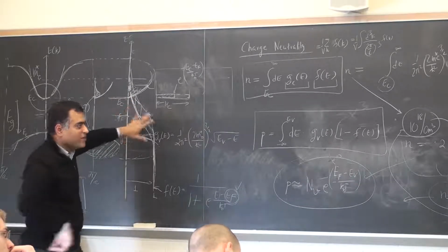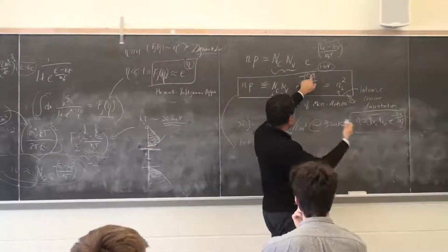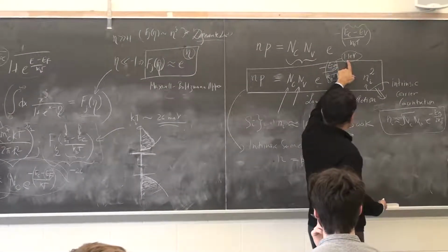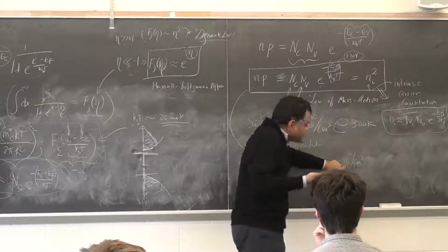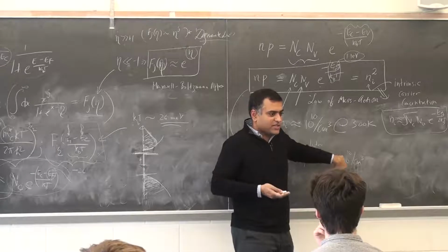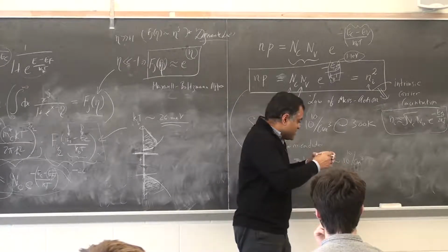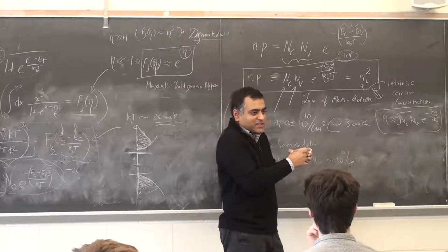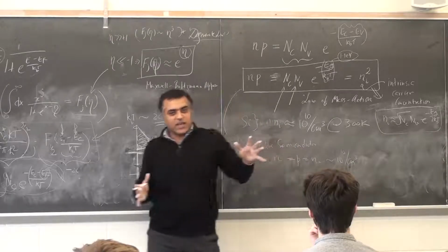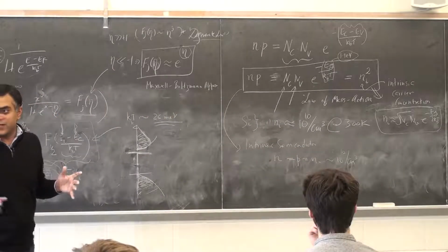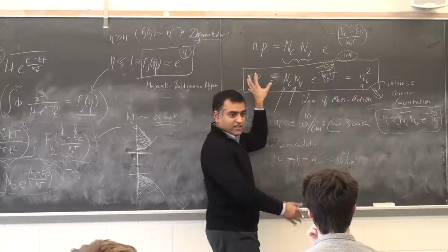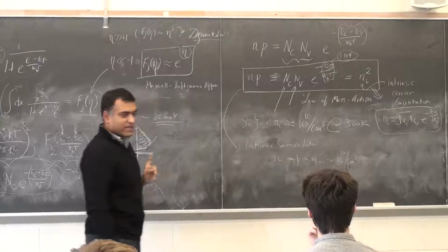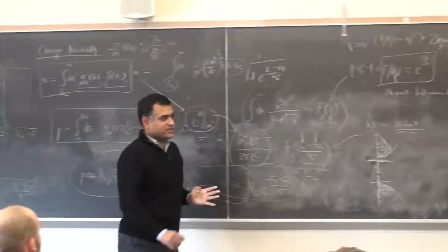If you have a very wide bandgap semiconductor, instead of silicon, let's say gallium nitride at 3.4 electron volts, you will see that when you go from 1 eV to 3 eV, the carrier density will be 10 to the power -10 or so per cubic centimeter, which means that in 1 cubic centimeter there is no electron in it. This is extremely insulating. So the wider the band gap, the easier it is to make it insulating. The narrower the gap, the larger the number of free carriers at room temperature, so it's harder to make it insulating. That's why graphene is very hard to make insulating.